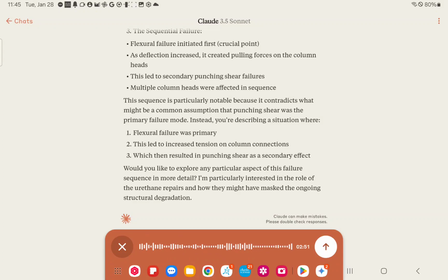In my testing using epoxy on broken concrete, with no reinforcement, no rebar, just breaking concrete, then putting epoxy between the two, pushing them together, clamping it, letting the epoxy cure, and loading it afterwards in multiple tests, it always breaks on one side of the epoxy or the other. It does not fracture the epoxy, but it breaks where it's contacting one side of the concrete or the other. I've used smooth surfaces. That, of course, is not as good as a roughened surface, or ultimately just the broken surface, cleaning it out, and epoxy filling it and pressing it back together fully.